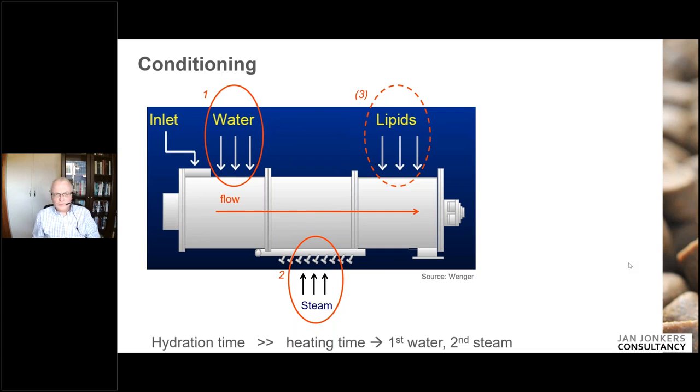Then in addition, it is quite good to add the water at the top of the conditioner and steam at the bottom. Water wants to go down, steam wants to go up. So then you get a good interaction of all the injections with the particles.